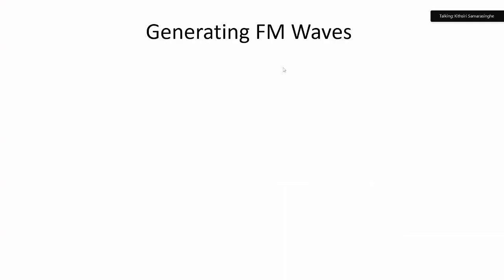Okay, now that we know the principle of FM and PM also, and under FM we discussed narrowband, and why narrowband is very important, especially for professional mobile radio systems, because it saves bandwidth but gives sufficient quality for the purpose, but not the best quality. So we have sacrificed quality to minimize the bandwidth in narrowband FM signals.